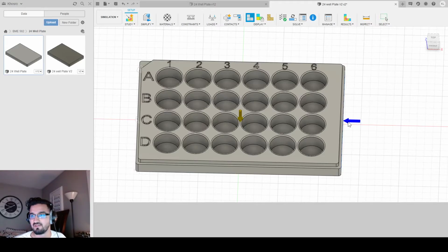But yeah, it's about where I want it to be. But instead of, let's just make it the full surface. Instead of 244 pounds of force, we're going to go back to newtons. And we're going to change this to 10,000 newtons. So this should pretty much crush my plate, right? Go to pre-check. We're good to go. Results. Simulate the results.